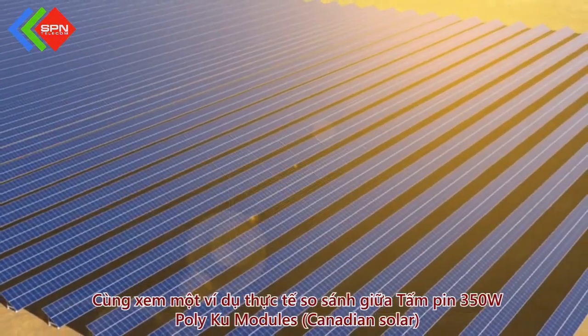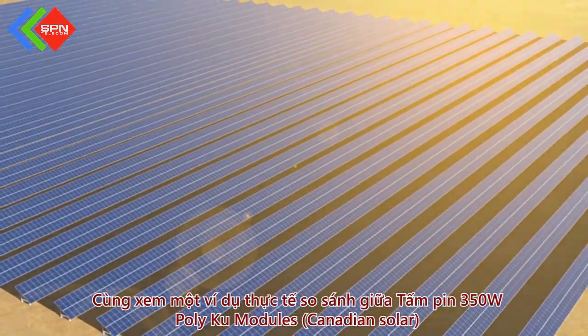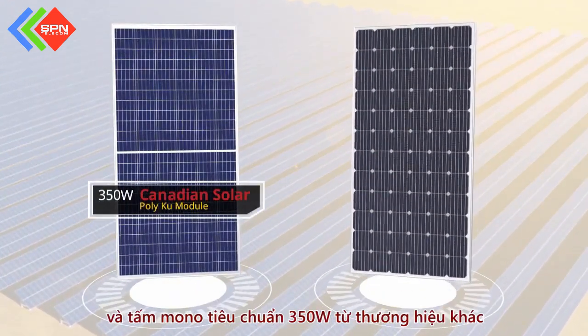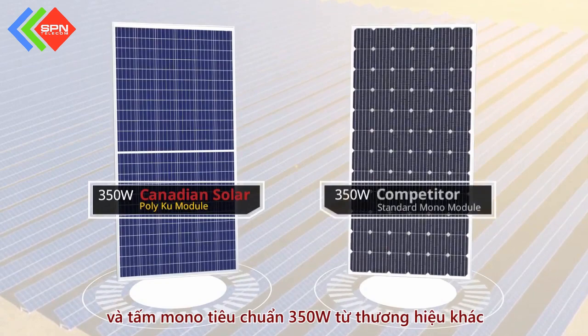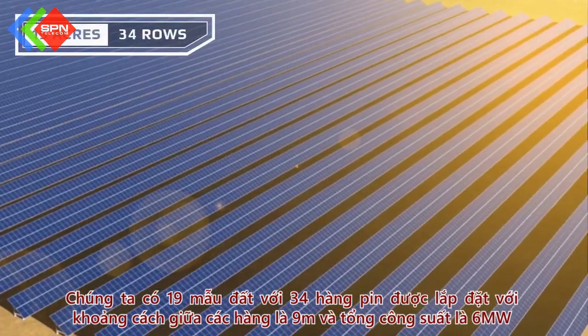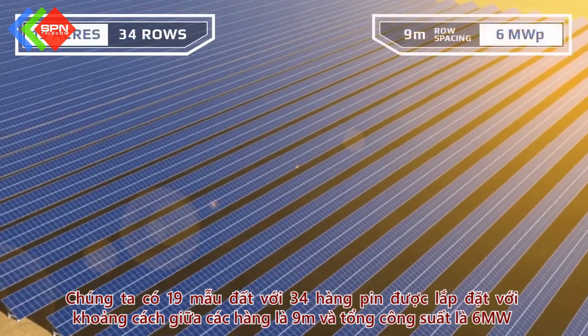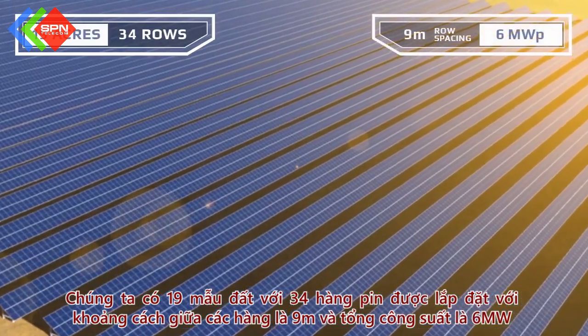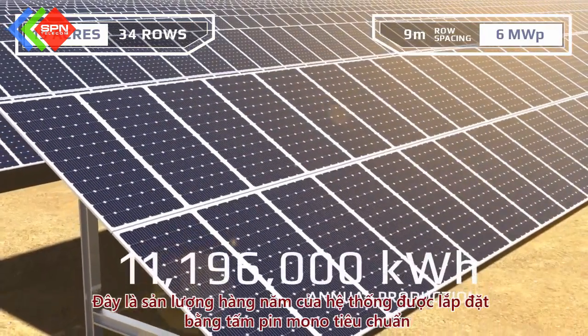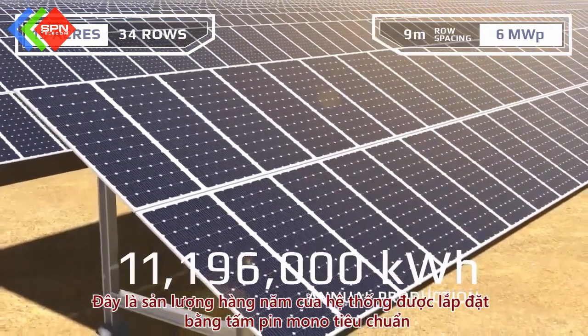Let's look at a real-life design example, comparing our 350-watt Poly Ku modules to our competitors' 350-watt standard mono modules. We've got 19 acres of land, which fits 34 rows of modules, with 9 meter spacing between the rows for 6 megawatts total. Here's our competitor's standard mono system.